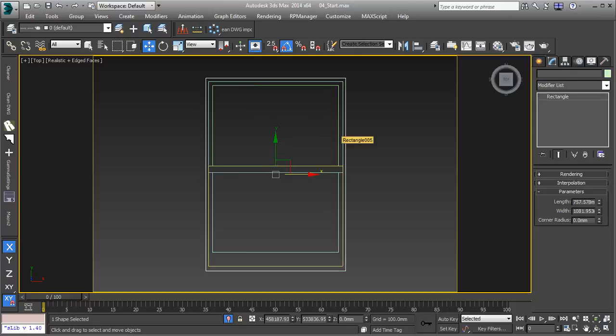Now quite a cool thing is obviously there are two splines in exactly the same place. This edge and this edge were in exactly the same place. So that's not the one that I want, but if you click and click again, it cycles through everything that's underneath that particular mouse click. So if you're in any viewport, perspective, top or side, and you know your object is exactly there, but it's selecting objects in front, just keep clicking, and eventually Max will find the one that you want. So I'm just going to keep clicking. There we go. That's got the one that I want.